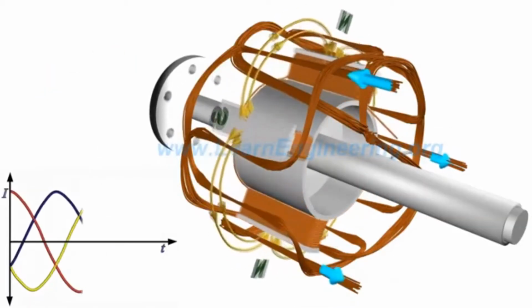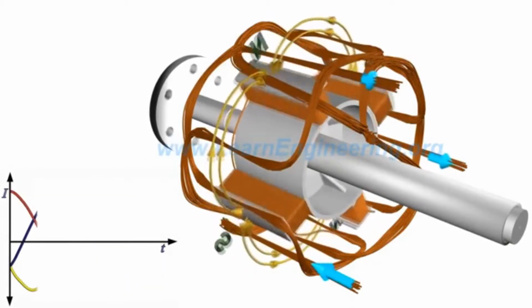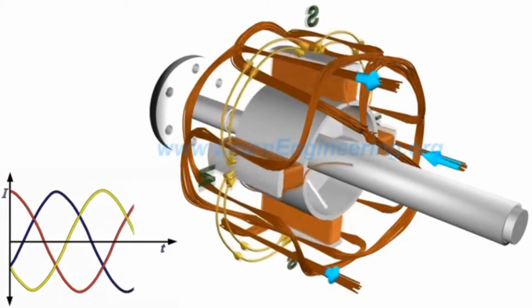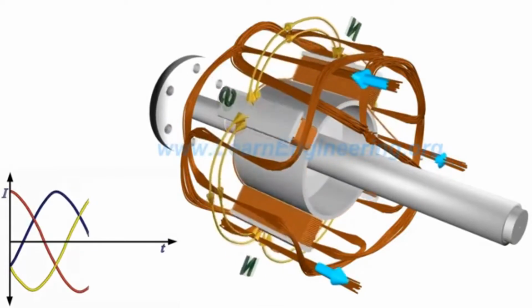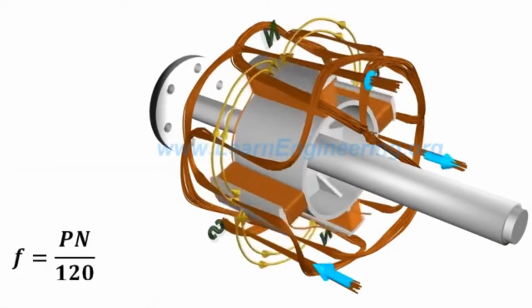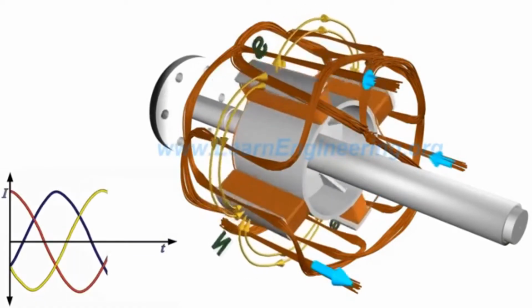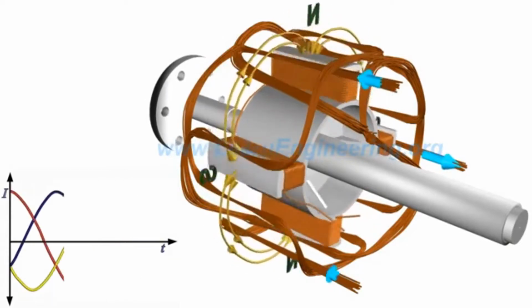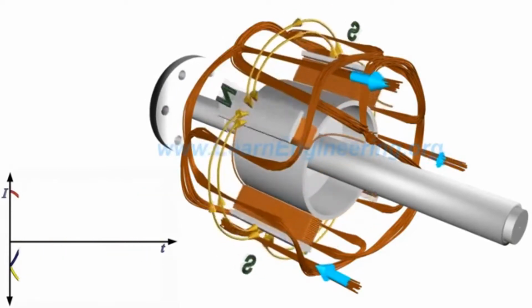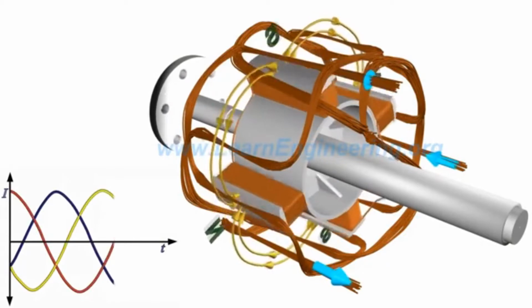For producing 3-phase AC current, 2 more such armature coils, which are in 120-degree phase difference with the first, are put in the stator winding. Generally, one end of these three coils is star-connected and three-phase electricity is drawn from the other ends.